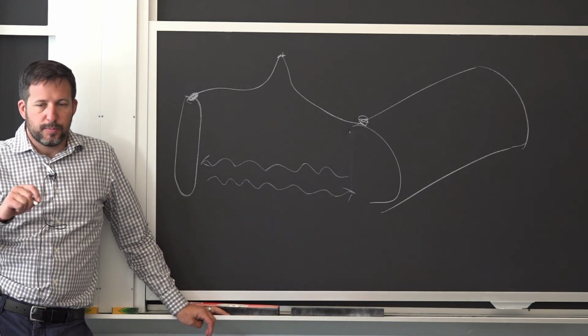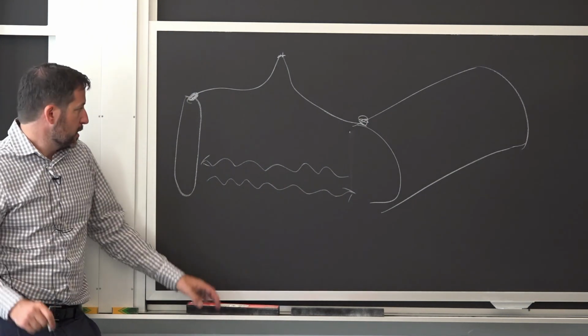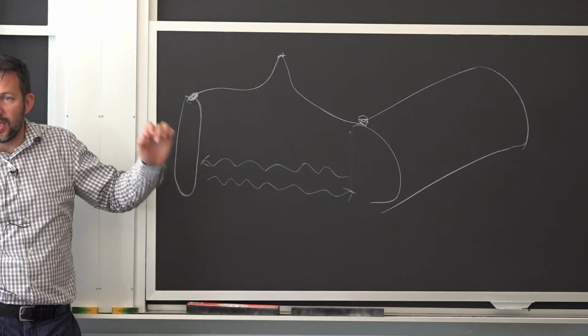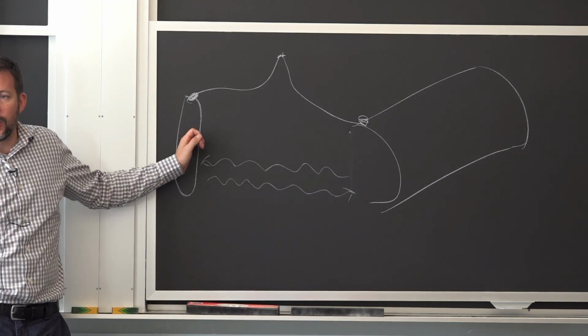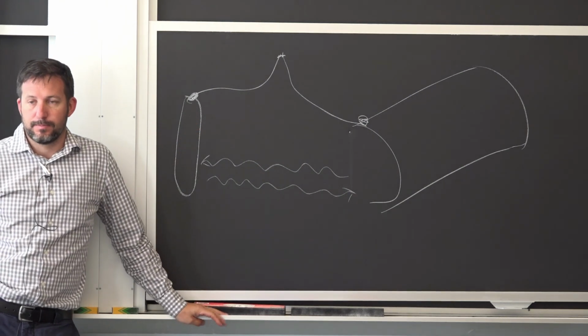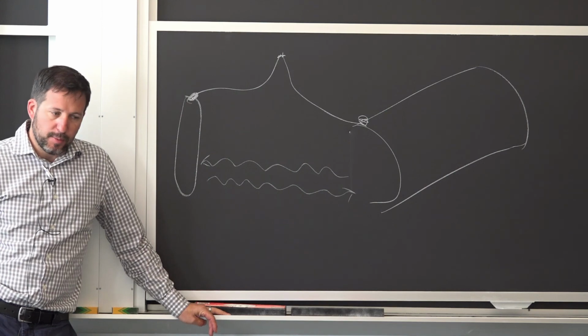There's no power supply here. It's just that this anode has a different potential. It has a different equilibrium potential in the same soil, and that's what makes the driver. So you're not even applying... No, you're not applying anything.